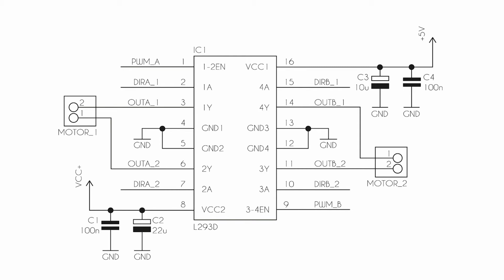The control is quite simple. The state given on input A is repeated at the output Y. If on 2 inputs A we set the opposite states and between the outputs Y turn on the motor, it will start working. When you invert both states at the A inputs at once, the motor will work in the opposite direction. Note that providing 2 high or low states does not create a short circuit risk.